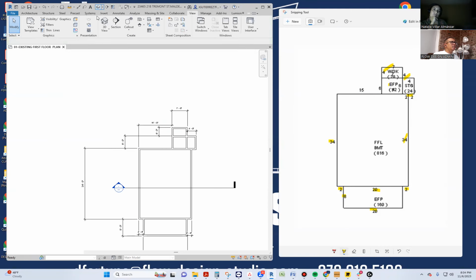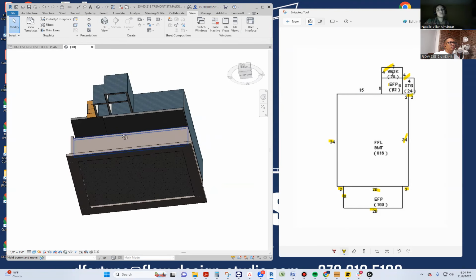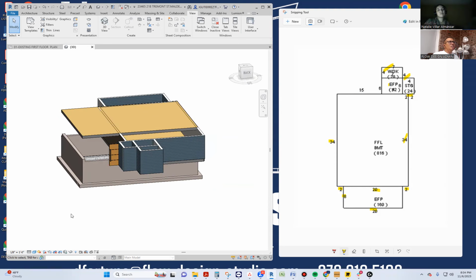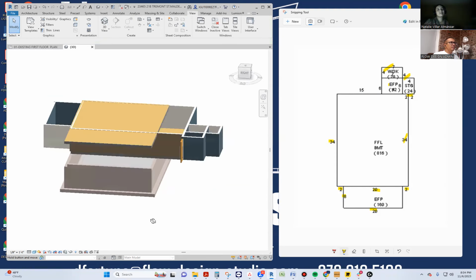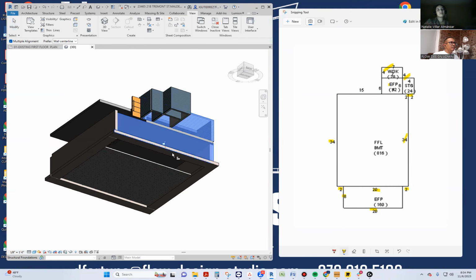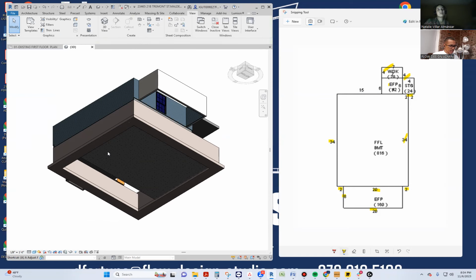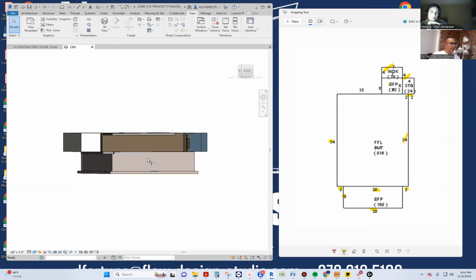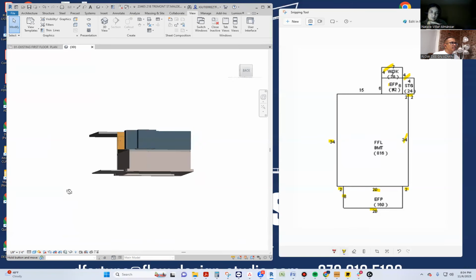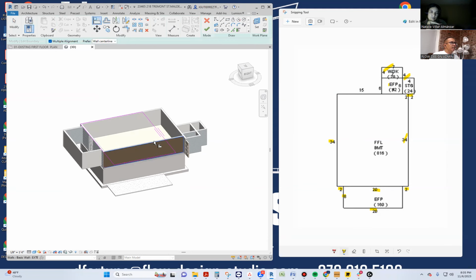And you're like, okay, what does this thing look like? Right now, it's a mess because our foundation walls didn't follow the rest of our walls. Not a problem. No big deal. You just align. That will align it. That's AL. That's aligning that. Then align again, that and that. Then AL, align this wall with that foundation. Generally, that's it. You see, that's starting to look better. This floor is floating around funny. Don't worry about it. Just align.